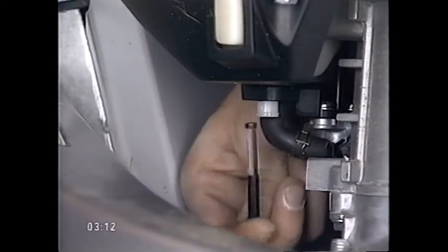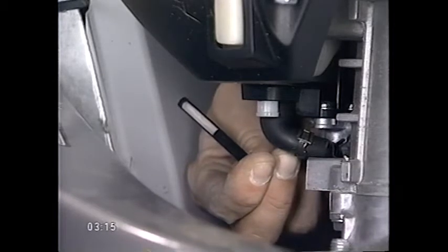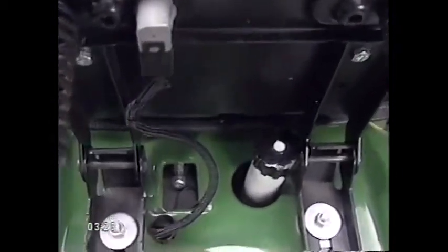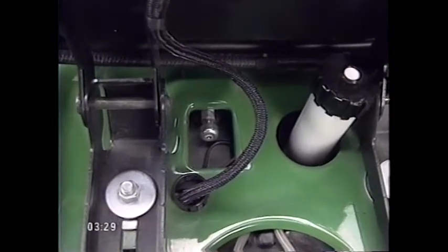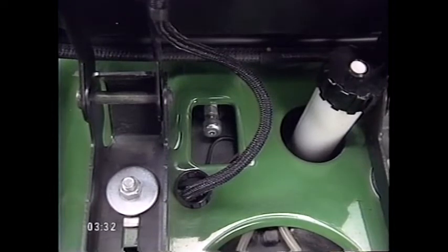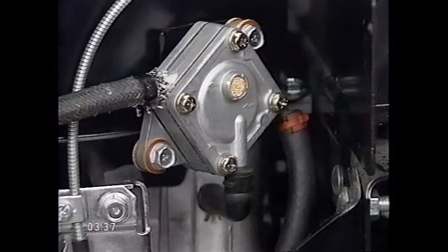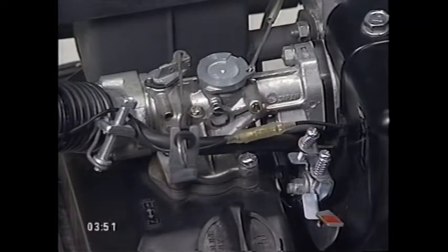Fuel tanks may have a screen on the fuel line pickup to prevent debris from getting into the system. And inline filters like this are also common. Most systems will feature some type of fuel shutoff valve. It can be used during long-term storage, during short-term draining of the fuel system, and also to prevent fuel from getting into the engine during transport. If a fuel pump is needed, Kawasaki engines commonly use a diaphragm pump that is driven by vacuum pulses received from the engine. The pump will either be mounted separately or it may be built into the carburetor itself.